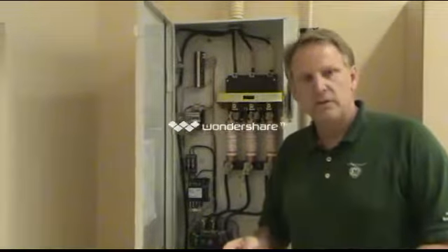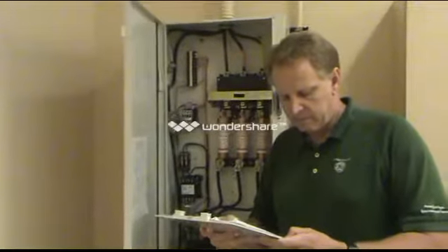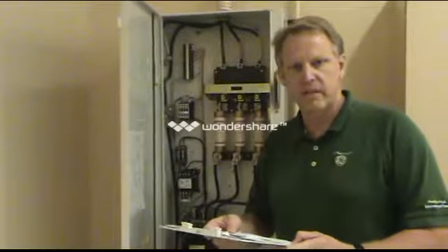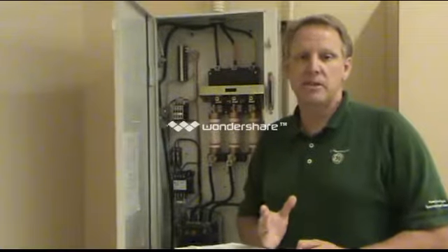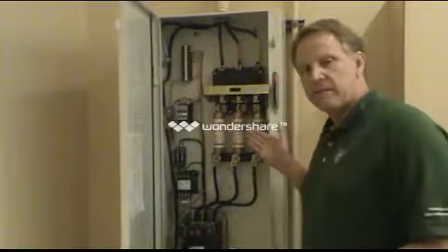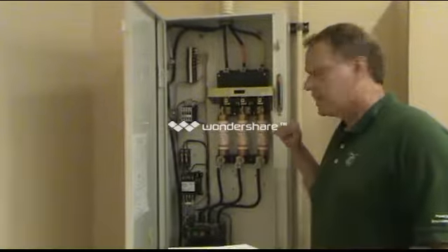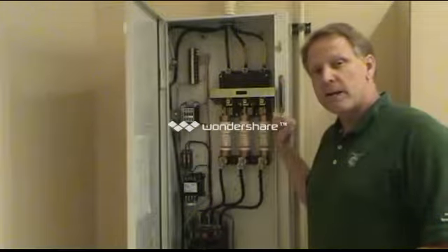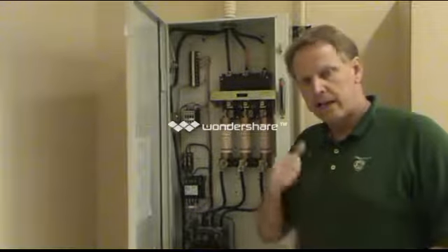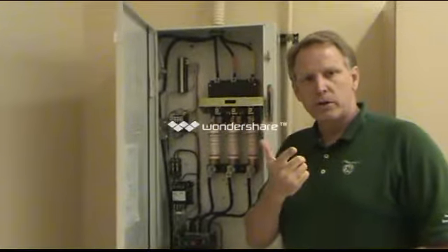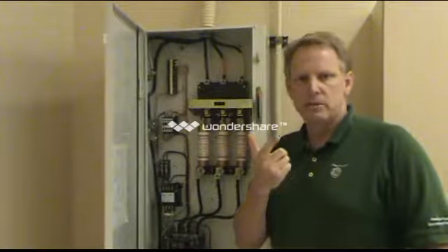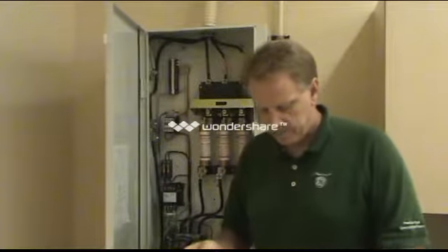Step 2, do the fuses and breakers meet the manufacturer's installation specifications? This is something you guys should know. 125 amps happens to fit the system that we're working on, so that would be yes. If you don't know that answer, there's a couple places you can take a look at: your pre-install manual or your blueprints, your E1 and your E2 pages.